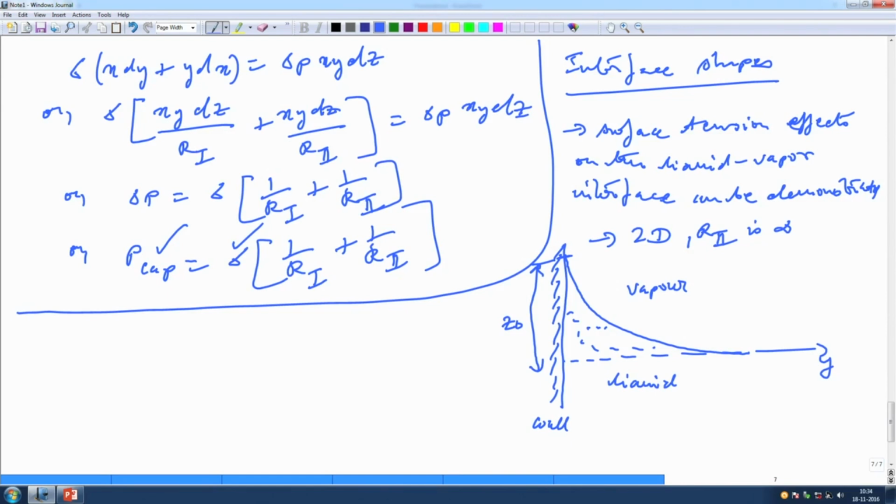So, you can almost consider that this particular problem extends infinitely into the board. It is an infinite wall, an infinite water source, or whatever liquid you can think of. This liquid wets this particular wall, it is a wetting liquid type, and it shows a curvature, and it goes up the wall for a distance of approximately z0, and there is gravity acting in the downward sense. It is a vertical wall and the liquid is wetting the wall, and one radius of curvature is basically infinite. Got it?